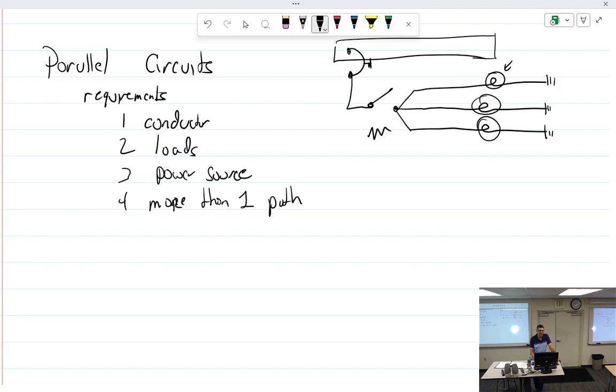Bypass the switch. Sure, you could bypass the switch, absolutely. Just take a nice piece of wire, bypass the switch, screw it in there. But let's just think. Check the resistance of the switch with an ohm meter. All right, that's what I want to hear. Check the resistance of the switch between poles.